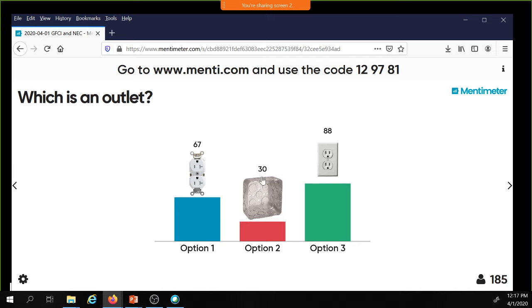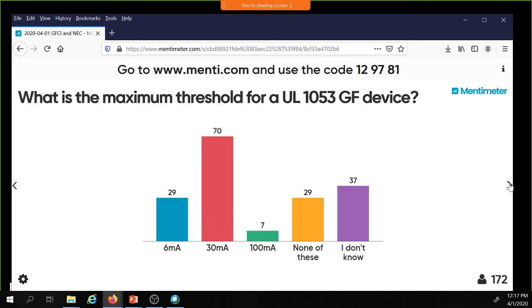Any outlet, which you see in option 2, any outlet that has a receptacle in it is now a receptacle outlet. If there's an outlet, which is in option 2, that has a light fixture in it, it's a lighting outlet. So you have to understand the terminology and how that term is used in the NEC because some of the requirements will say either receptacle outlet or outlet, and there are some recent changes in the NEC that will demand you understand that. So I guess you could call that somewhat of a goofed up question on my part, but I got my point across, didn't I?